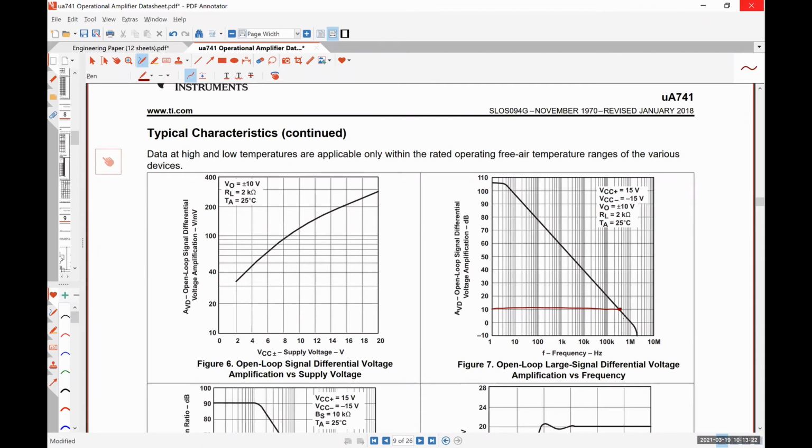And we also have another figure of merit here. When we're looking at our frequency where the gain is 0, this is FU, the unity gain frequency, because a gain of 0 decibels is exactly equal to a gain of 1 volt per volt.